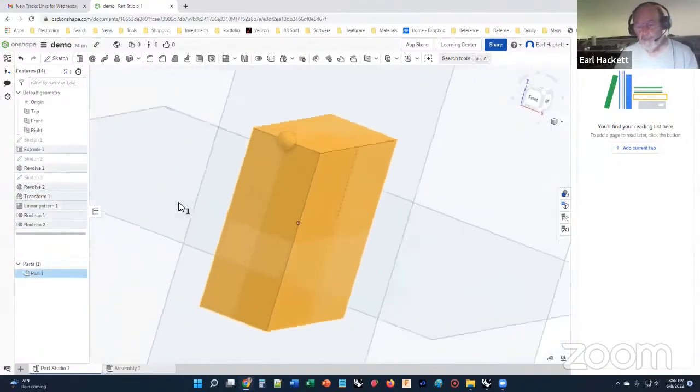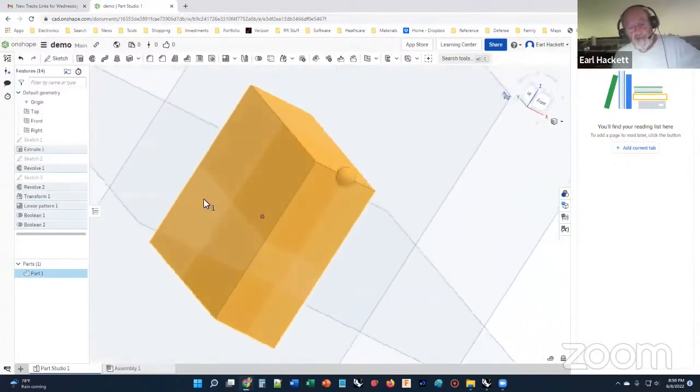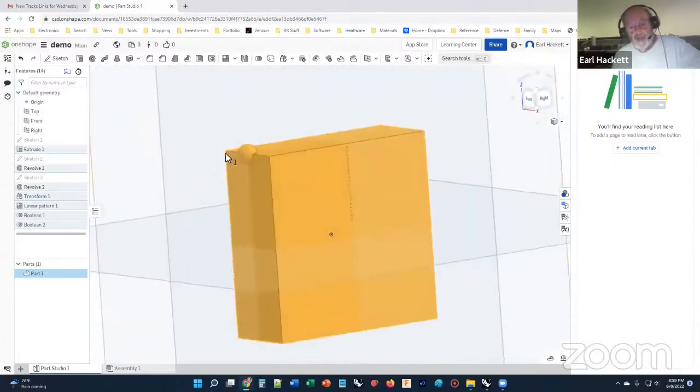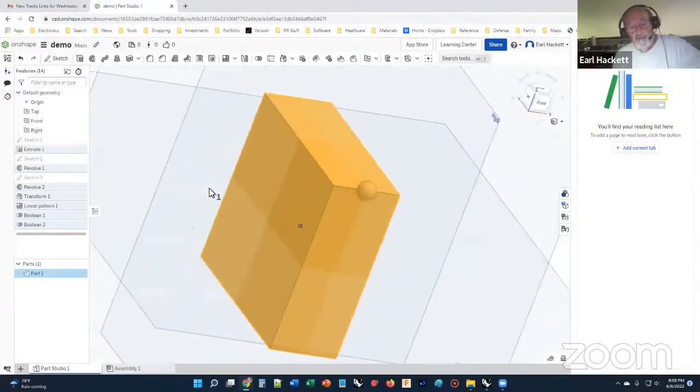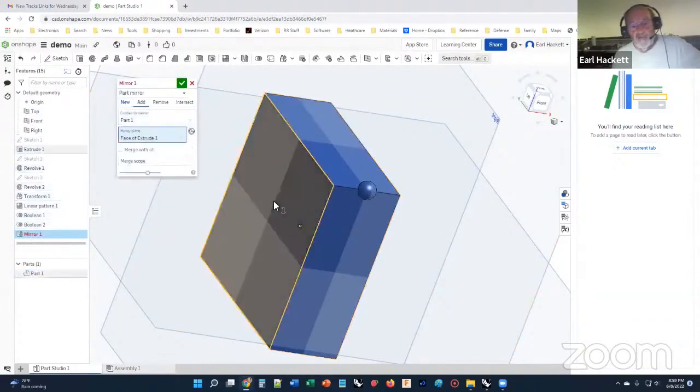Now, when I built the original, and I'll show you the original, I started with Fusion 360. And I built the main girder by drawing a 1/8 inch portion of it. And I mirrored it back and forth and over and under to turn it into the full size girder. And you do that by going over here. So we have rivets on this side, this guy here, just to keep track of where I am. So I'm going to mirror part 1, mirror plane, this surface here,